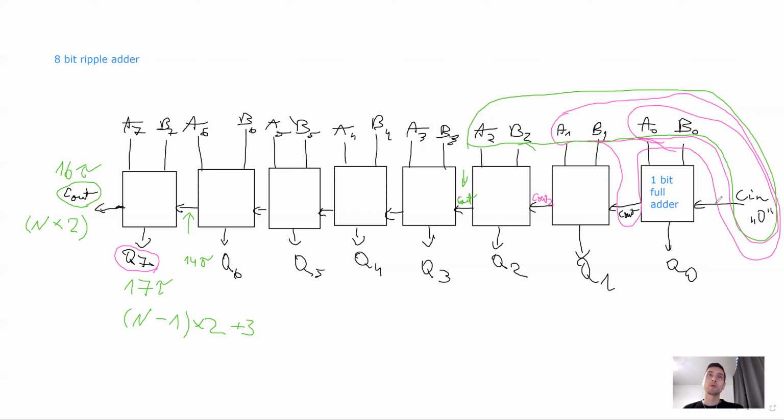And the simplest, most basic thing would be to create a large truth table where we write all possible A and B combinations and carry in combinations. And then we write values for each carry out. Then we draw a Karnaugh map for each carry out. And then we construct for each carry out a logic circuit which accepts all bits of A, all bits of B, carry in 0, the first position, and produces the carry out for each position, right? And we would just copy them. And so it's possible to build something that calculates all carries only from the inputs without the middleman.